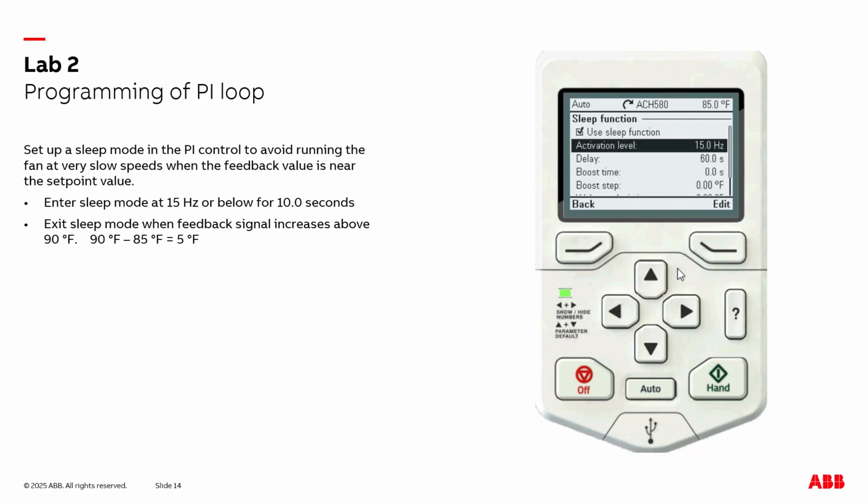And the delay time is 60 seconds. Here, we're going to edit this and make this 10 seconds. Now, boost time, we're not being asked to set that up, so we'll ignore that. Now, wake up deviation down here. Wake up deviation by default is 0 degrees Fahrenheit.